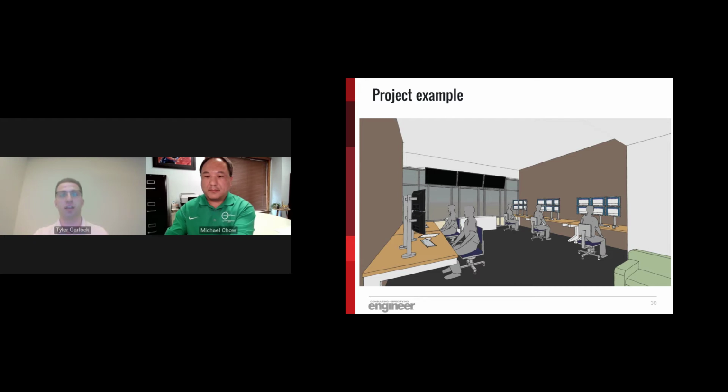But also, those downlights are very direct luminaires. So they're going to create shadows on the people's faces, especially under the eyes, under the nose, which are really key components to being able to read lips or understand if the quality of the audio is not very good, or if you're visually or hearing impaired, that sort of thing.